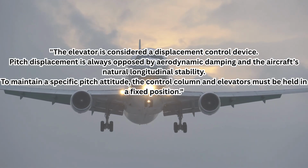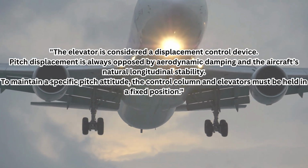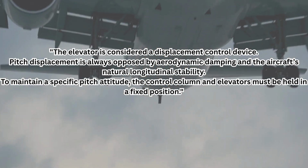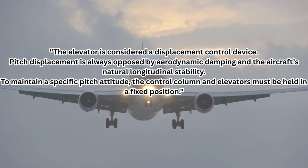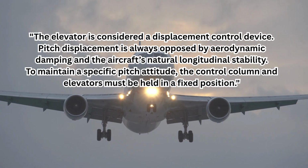The elevator is considered a displacement control device. Pitch displacement is always opposed by aerodynamic damping and the aircraft's natural longitudinal stability. To maintain a specific pitch attitude, the control column and elevators must be held in a fixed position.